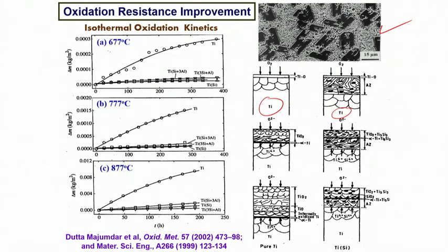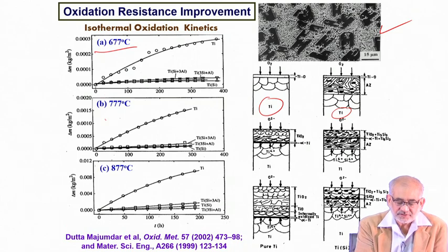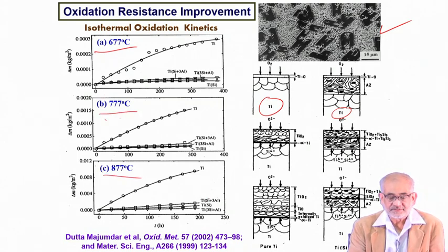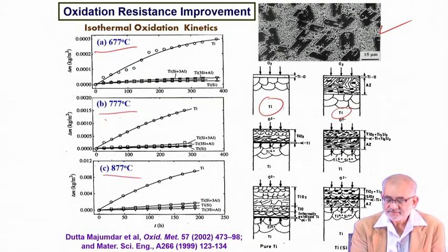you expose it to temperatures like 400 or 500 or 600 degrees centigrade, it merely reacts with oxygen from the atmosphere at high temperature and creates a titanium oxide layer, which is fairly porous and non-adherent, and it spalls off and exposes pure titanium. So in the process, this titanium substrate is lost increasingly because of this oxidation attack from the atmosphere at high temperature.